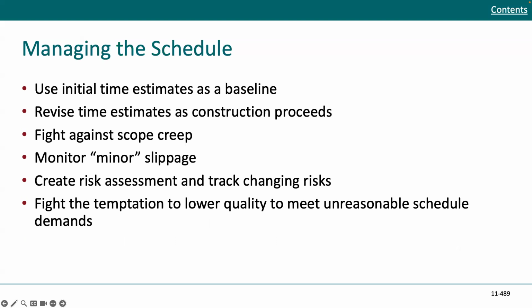You want to be managing the schedule. You want to use the initial time estimates as a baseline. You want to revise time estimates as construction proceeds. You want to fight against scope creep. It's always important to monitor the minor slippage and nip it in the bud as soon as possible. You want to create risk assessments and track changing risk. And finally, fight the temptation to lower the quality to meet unreasonable schedule demands.